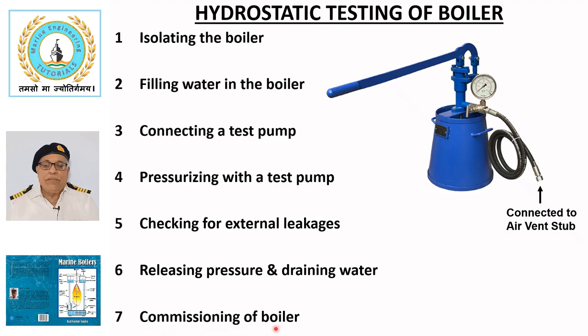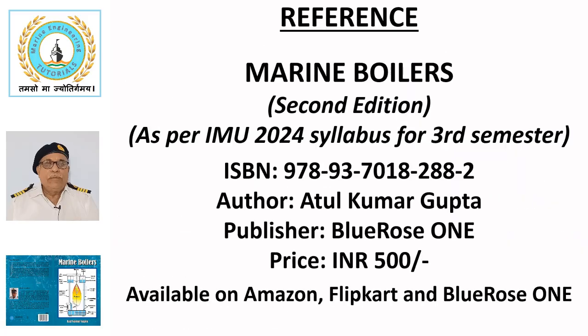Commissioning of boiler. Upon satisfactory completion of the hydrostatic test, the boiler is relieved of the pressure and water is drained. All mountings are connected and the boiler is commissioned after floating the safety valve. This completes the study of destructive and non-destructive testing conducted on boilers' pressure parts.